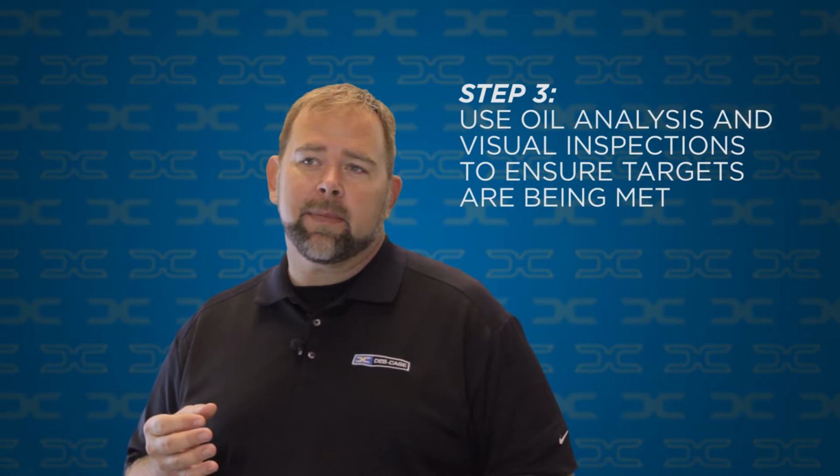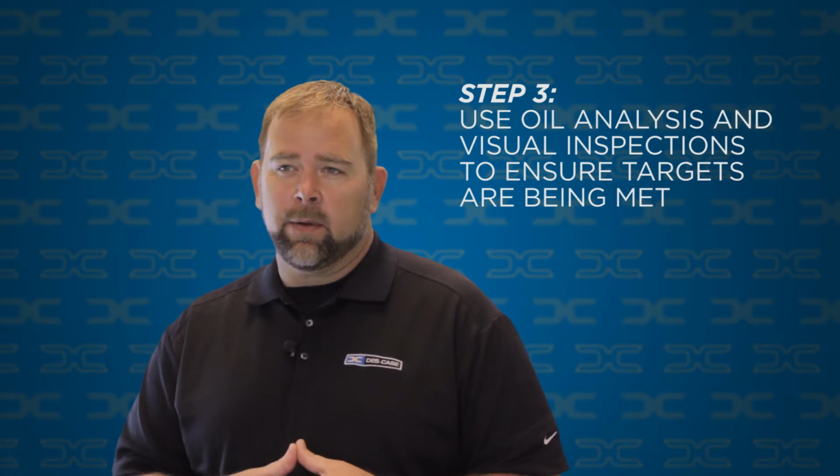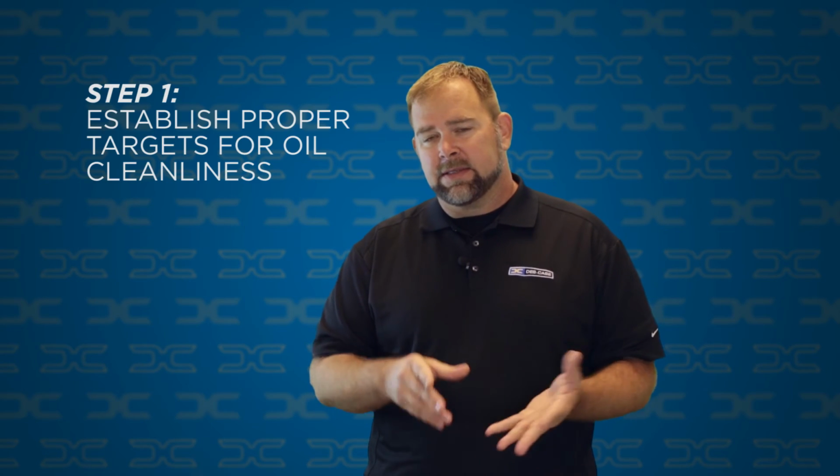But no matter what we employ, we need to be able to verify that these things work, and that's the 3rd step. The 3rd step is to measure the contamination in the oil to see if we're being effective. For particle counts, that means good sampling. We have to take good samples so that we get valid particle counts, but we also want to have repeatable, consistent data so that we can make sure that we're consistently meeting those targets. For water, it means doing the right test. We need to make sure that the tests we're doing for moisture are sensitive enough to measure water below our target moisture limits.